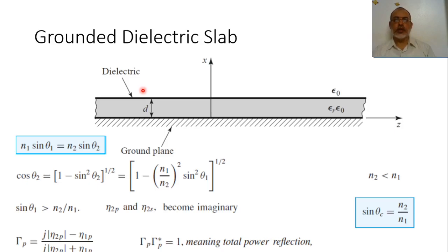And we said that in the case of parallel plate waveguide, the TE and TM waves can be represented as multiple reflected waves between the two interfaces of the parallel plate waveguide. In the case of the parallel plate waveguide, we have two conducting planes separated by a dielectric material, and this dielectric material can be air.